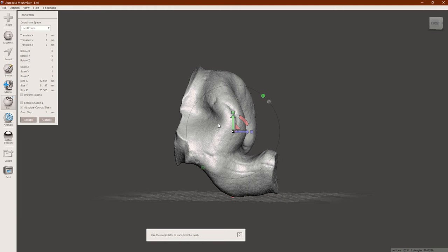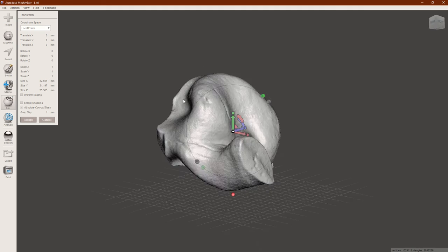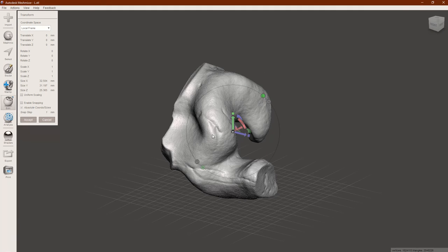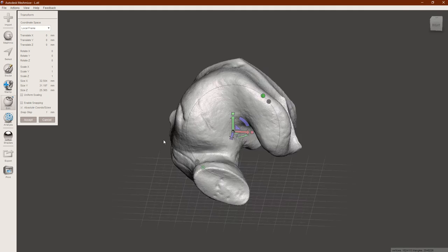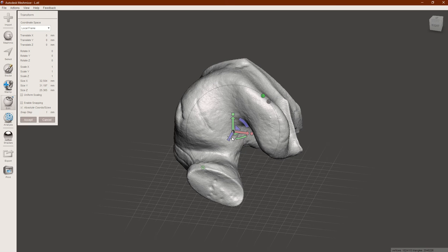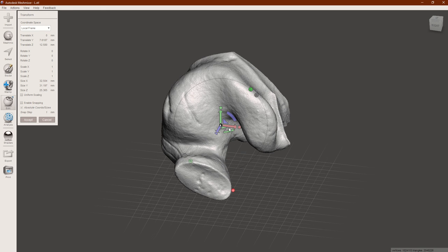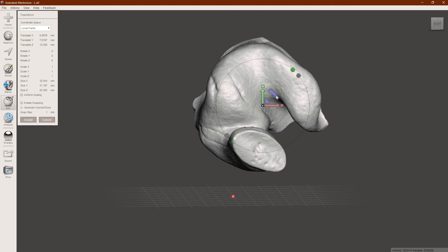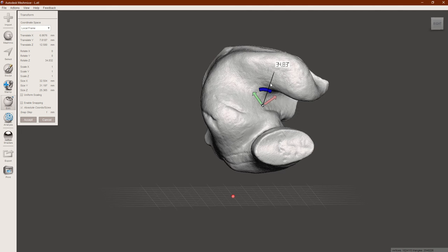And just a quick note on MeshMixer, if I hold down my right mouse button and I move around, that pans my camera viewing around. If I were to look at these arrows, I would be able to drag them, three-dimensionally, to wherever they go. And these little circles, or rays or something, I could actually rotate the shape with.